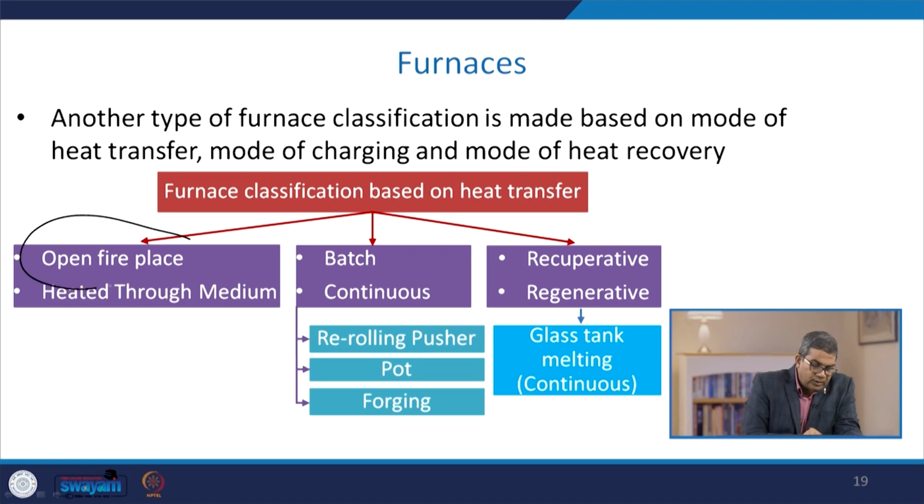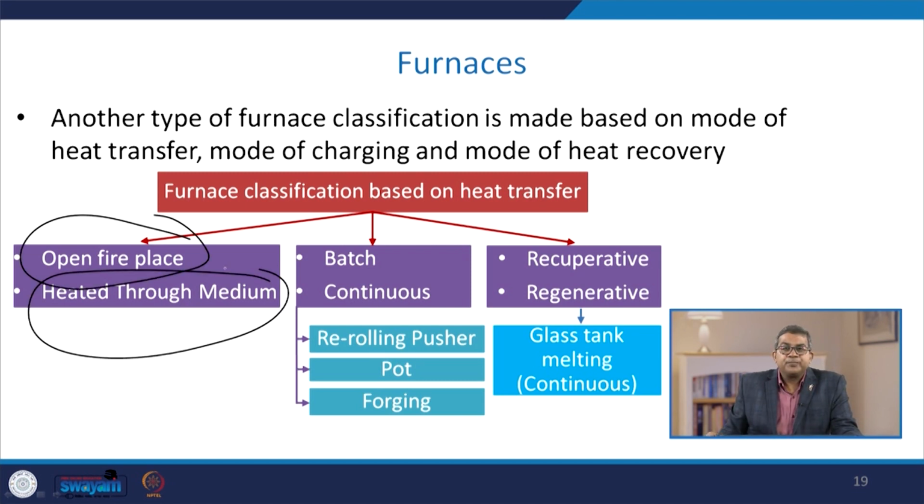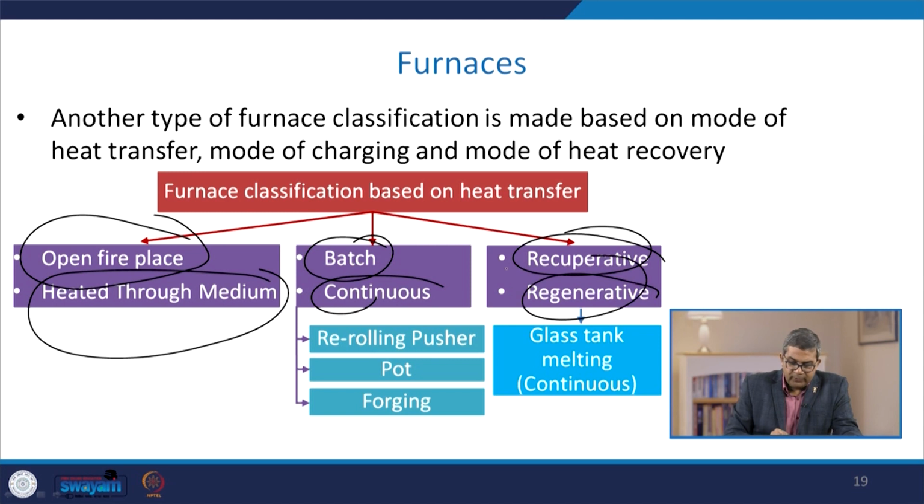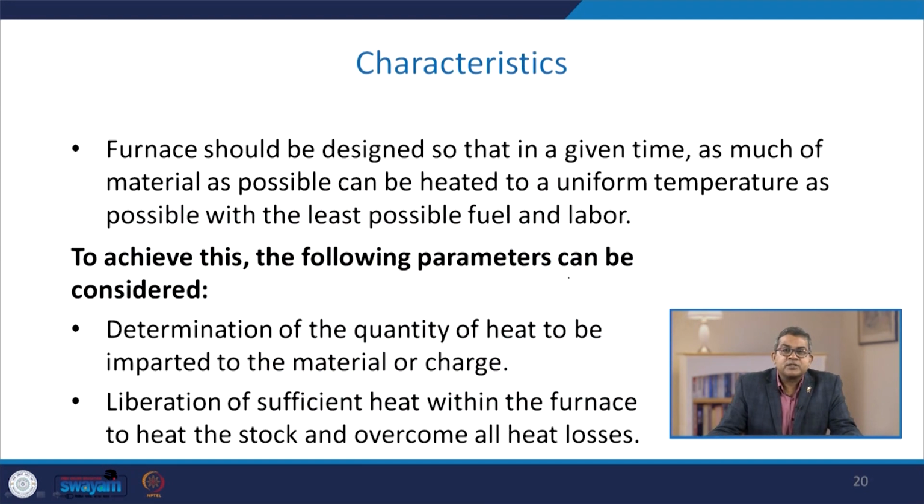One is based on the open fireplace and the second one is heated through a medium. Another classification is batch or continuous, then recuperative and regenerative. Further, this classification is subclassified into re-rolling type pushers, pot, forging, and recuperative and regenerative type glass tank melting continuous operations.